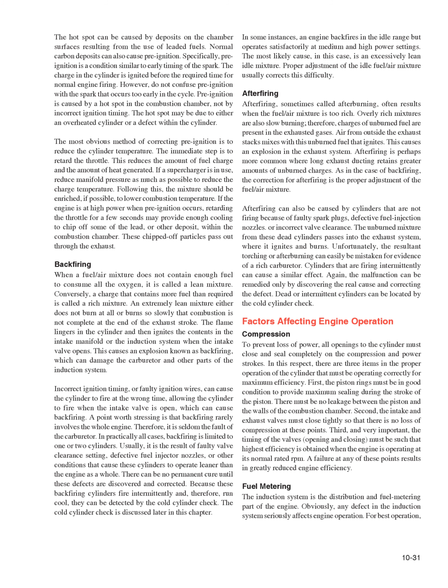Backfiring. When a fuel/air mixture does not contain enough fuel to consume all the oxygen, it is called a lean mixture. Conversely, a charge that contains more fuel than required is called a rich mixture. An extremely lean mixture either does not burn at all or burns so slowly that combustion is not complete at the end of the exhaust stroke.